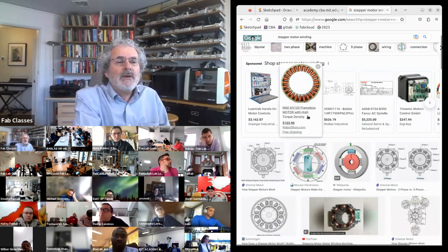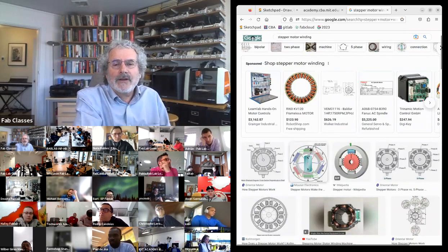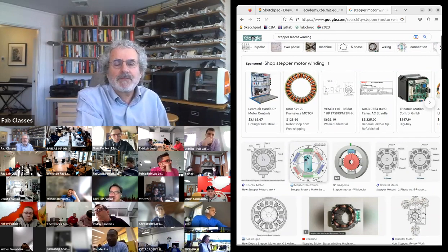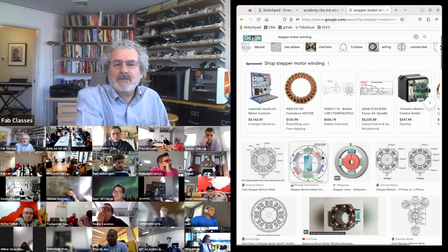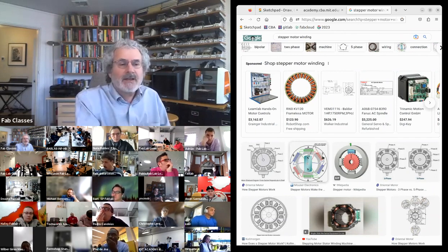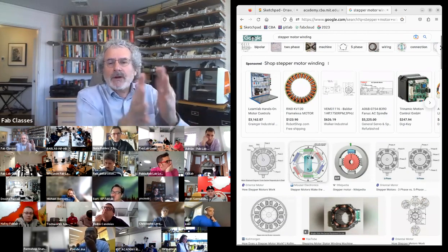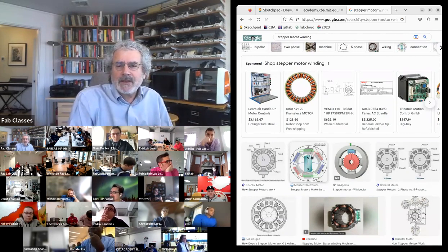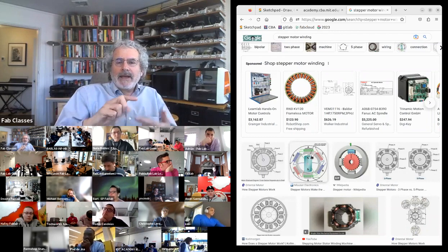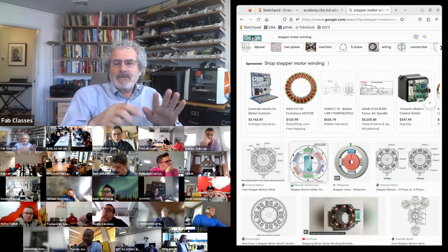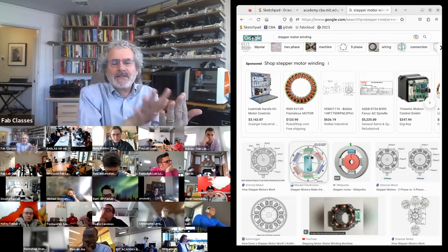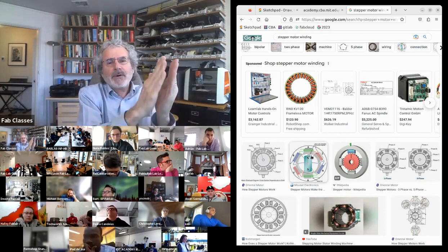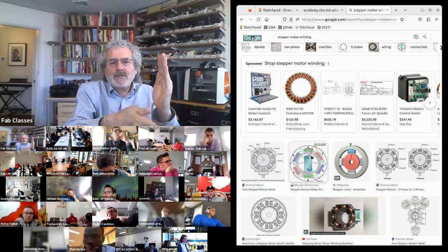So for any one setting of the current, there's a direction where the magnets are happy. Then if I move the current to the next set of coils, the magnets aren't happy where they were, they want to align with it. And so by continually toggling between the steps in the current, I can pull the magnet successively to each coil.